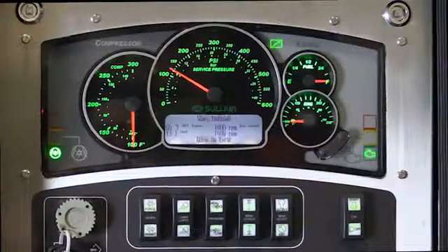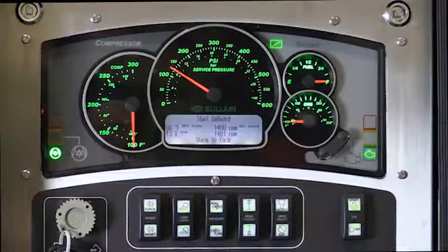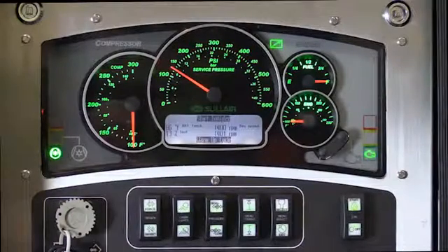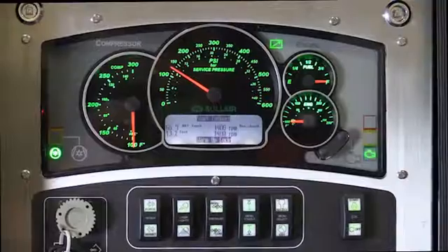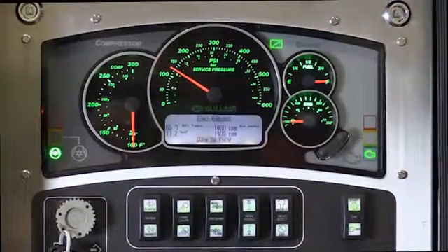If the compressor does not start on the first crank cycle attempt, it will by default programming automatically attempt 2 more crank cycles. If the compressor has not started after the third automatic crank attempt, it will display on the LCD screen and store in the shutdown history an overcrank condition.